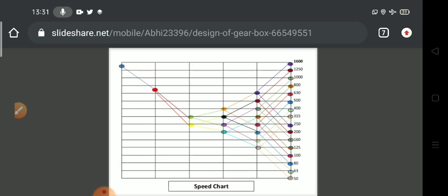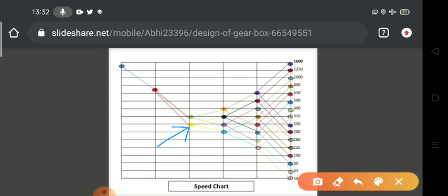Then another two spindles are connected with 4 speeds, right? Let's explain how you can draw the 4 speeds. This speed is 250, right? So we have to multiply 250 by 1.25, whatever value you get, you have to connect with that, and the other value you get by dividing by 1.25, then the second is connected here.